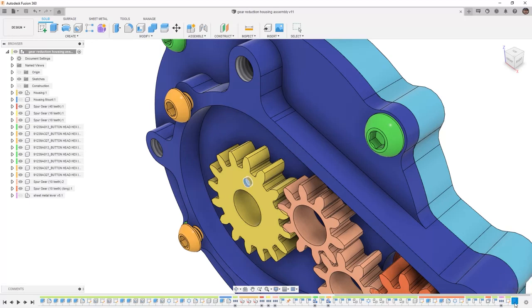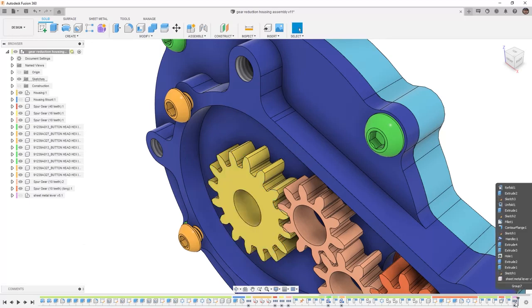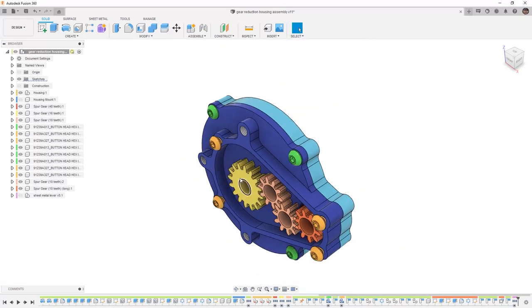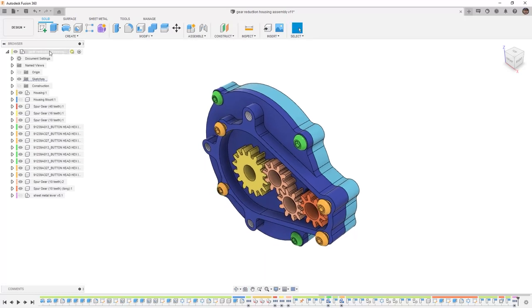We're going to select and delete that sketch and that extrude because we want to make sure that we keep this gear how we designed it using that script. But it is important to understand the functionality of those external designs coming into your assembly, as well as the context of taking some elements of your assembly and taking them outside as a derive. Once you're done playing around with that, let's make sure that we do save this before moving on to the next step.